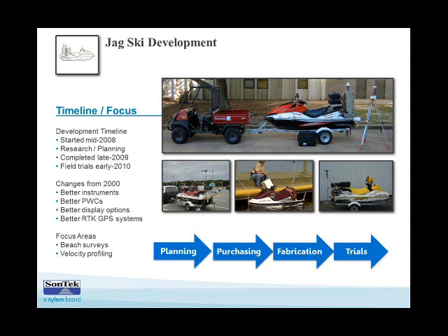What you're actually seeing, there's probably some delay coming through, but it was just a video snapshot of a flood tide of the water coming in. And if you pay real close to the bottom, if you'll click that one more time for me so we can replay the video. At the bottom, you'll see some sediment billows coming up. The velocity coming through here, and you can actually see some little hydraulic jumps forming in the channel. It gets well over 1 meter per second, sometimes 2 meters per second.